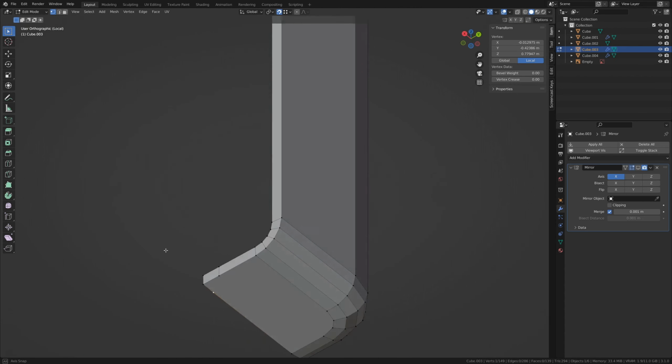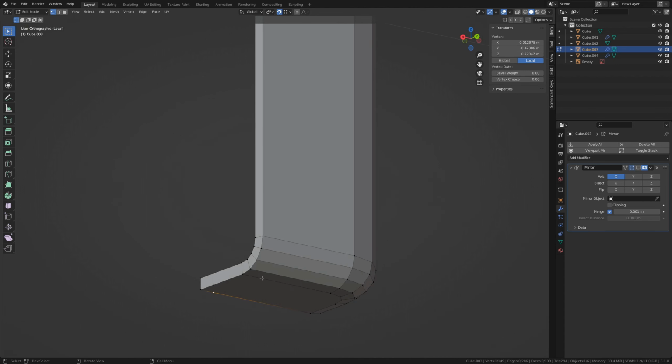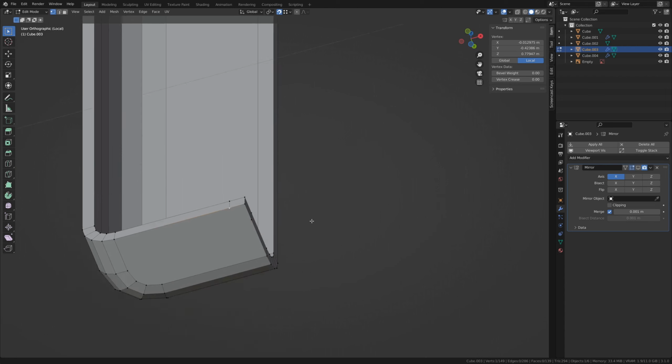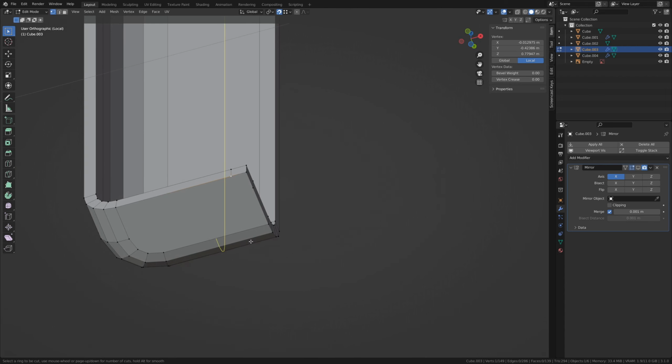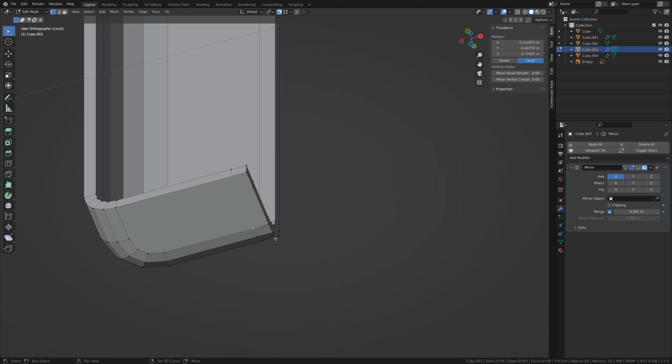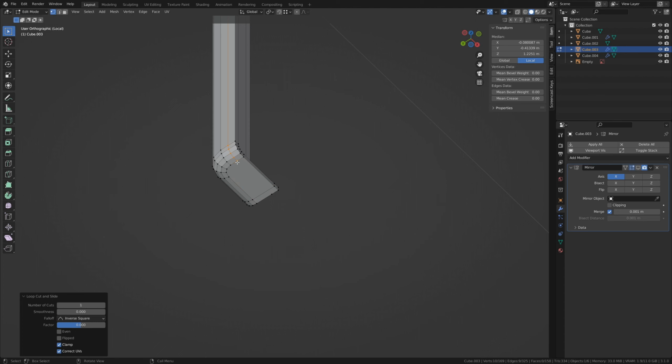And at the bottom, we're going to have nothing to connect this to at the moment. So we can add another edge loop, bring that over here, and then just move it manually with snapping turned on. And once you have this space here that you want to fill in with an edge, select the two vertices and hit J for join. Put another cut right there. And I can hit J.